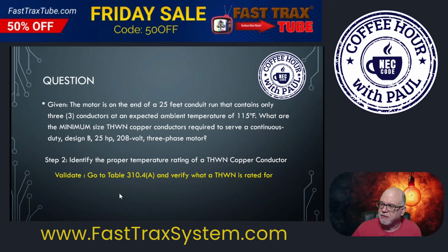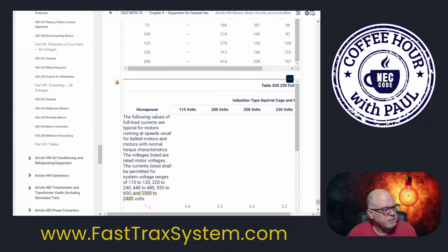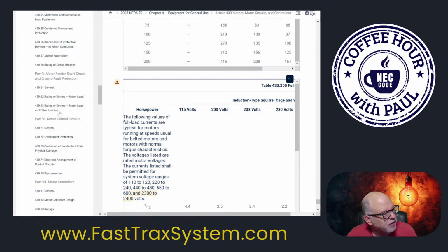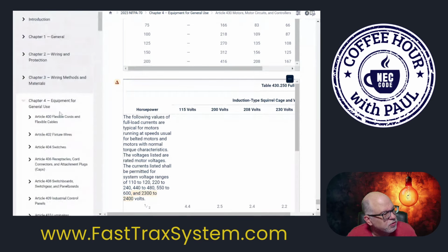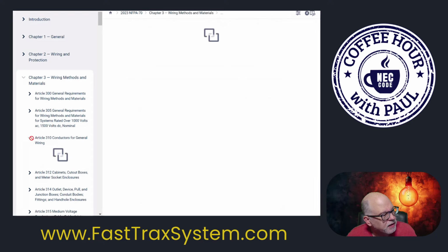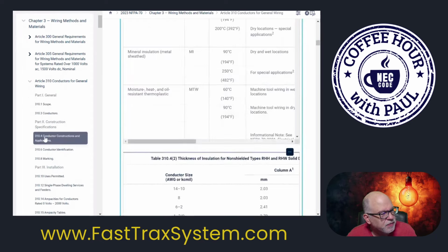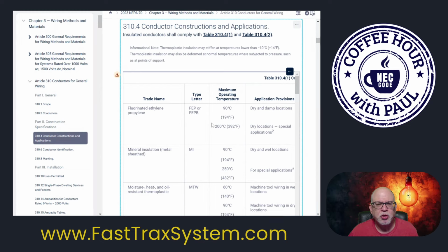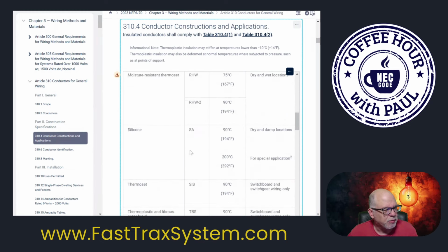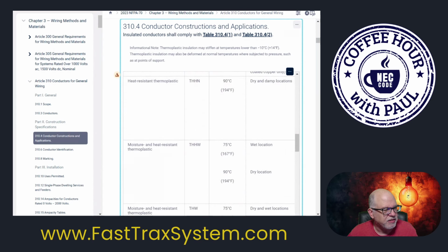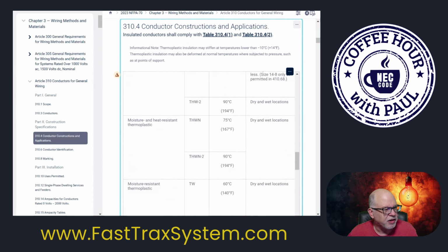So we're going to go to 310.4(A), and we're just going to verify what the rating of our THWN is. Okay, so let's go back to the code, and I'm going to take us back. Bear with me here. I'll run us all the way back to 310, and then I'll get us to 310.4. Okay, hard to see this table, but you'll be able to see enough of it to understand where we're at. So we're going to go down the list here, and we're looking for THWN. There's THHN, there's THW, THW, there we go. THWN, dry and wet locations, 75 degrees C.